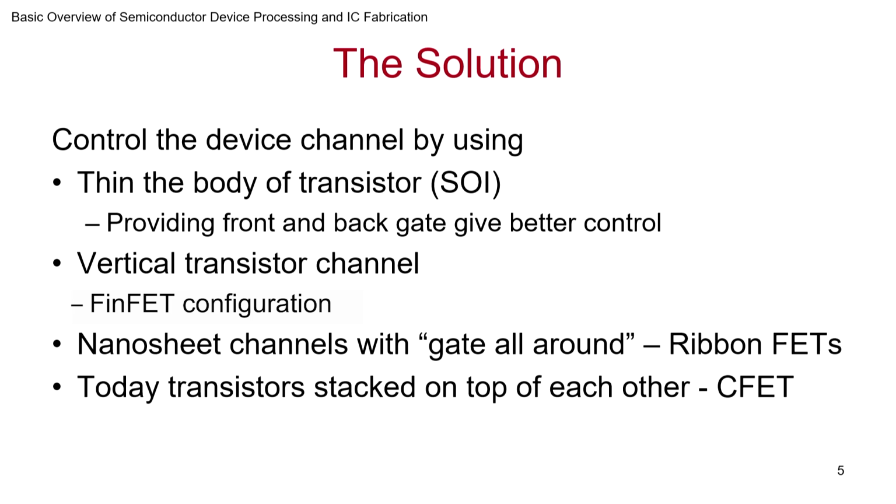And then following that, we find that as the transistors continue to scale, that is the whole thing about this technology, it continues to scale. So as you are reaching, say, 20 nanometers or something, you start using FinFETs. But what if it becomes less than 10 nanometers? Even that is not enough. So you have to go towards nano sheet type of devices, and this is essentially gate all around. Instead of just controlling from the top and bottom in the thin body transistor, in the FinFET you are controlling from 3 directions. In nano sheets you end up controlling from all around.